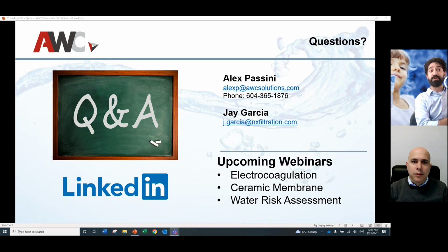And when you do, typically speaking, a UF and then an NF or an RO downstream, you are breaking that head. You're putting 1-2 bar into it. Many times you're going into some sort of brake tank and you're repressurizing. So there is a savings there in energy. Okay. I guess that kind of answers my energy question.